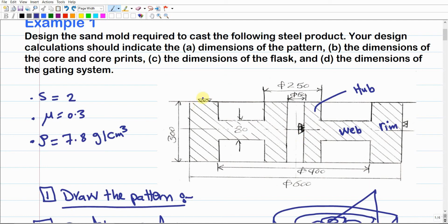So in case these symbols here are provided, this indicates that machining should be done. And this symbol could be any symbol. It shouldn't be just a triangular shape. It could be arrows, for example, that indicate there should be machining over this surface. Whatever it is, it's just any symbol agreed among the engineers and the manufacturers in the company to indicate machining. So in this way, we can apply these machining as already given here.